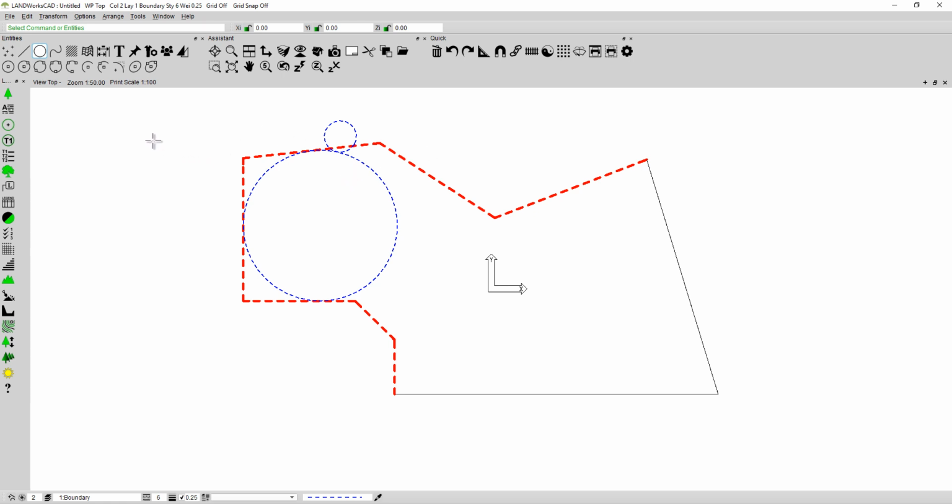So if I wanted to draw a curve, I would select the curve tools. Typically I would suggest you use this curve tool. It gives you a lot of control over how the curve appears. When you select it, rather than it going straight into the command, it's asking you to select a particular option. In this case, 2 is the degree of the curve that I wish to use, and I'm going to close the shape of the curve that I draw, select OK, and again follow the prompts.